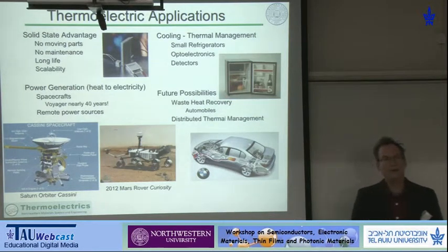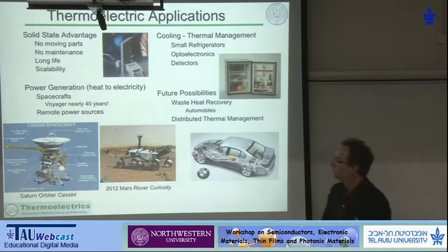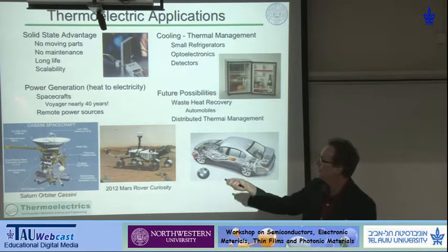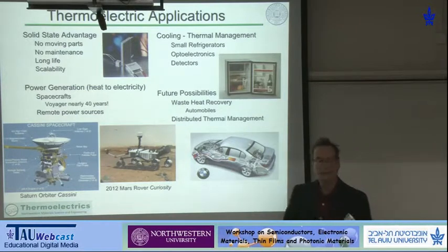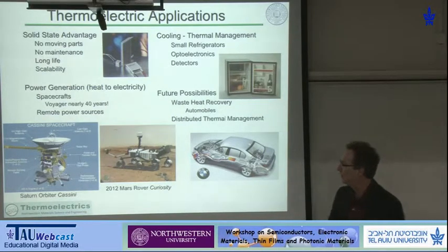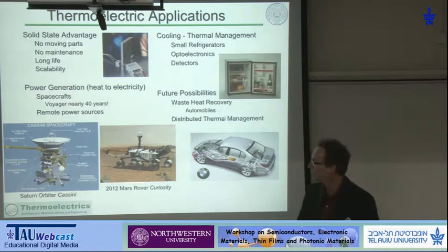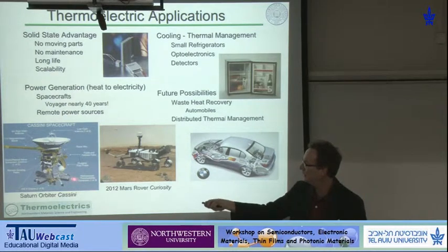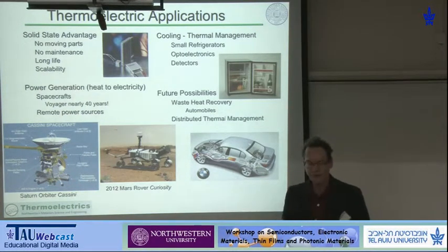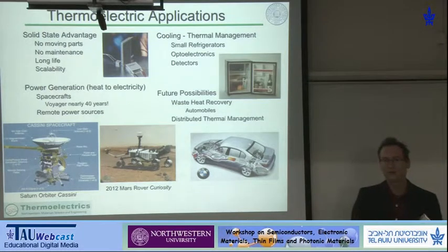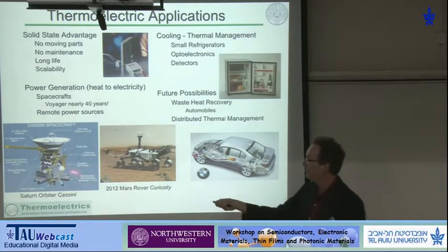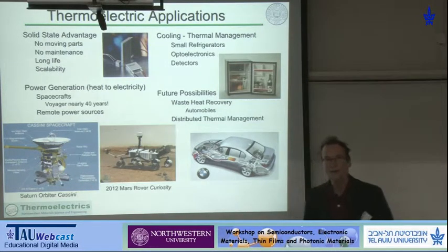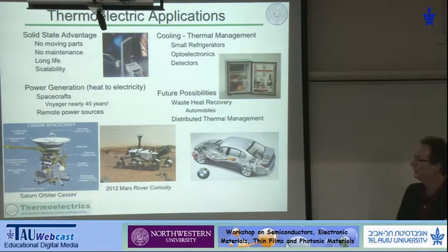For power generation, we've seen thermoelectrics in a number of different uses. I spent almost 10 years at NASA. We've been developing thermoelectrics for power generators for spacecrafts for a number of years. Here's the Cassini orbiter that has a radioisotope heat source and a thermoelectric generator that converts the heat from the radioisotope to electricity, which powers the communication and sensors for that spacecraft.